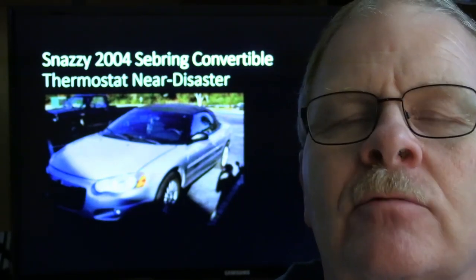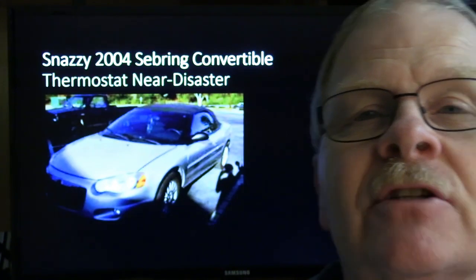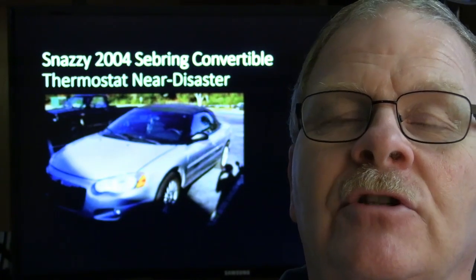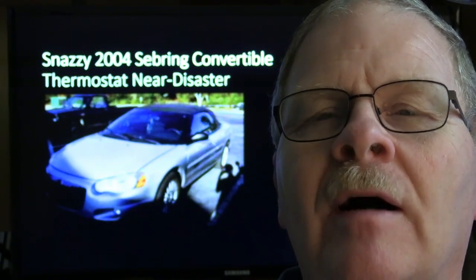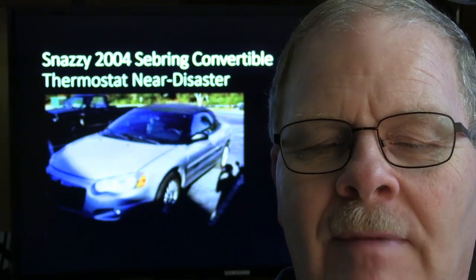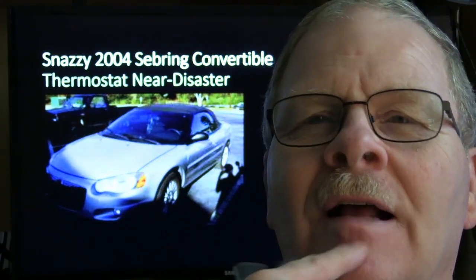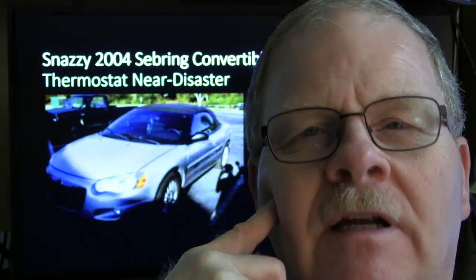Anyway, this one right here, this turned into a near disaster. A lot of you guys would be familiar with the 2.7 liter engines in these cars here. Don't you just love those 2.7s that have the timing chain driving the water pump? When Ford made this engine that's in the Edge, they've got the water pump down inside the timing cover being driven by the chain, but they weren't as smart as Chrysler was on this one.